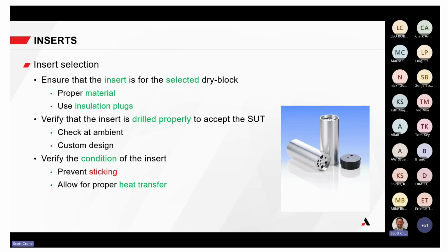Plus, you've got to make sure that the diameter matches. So typically, a high temperature and a low temperature won't match exactly. You want to verify that the insert is properly drilled to accept the sensor under test. Check it at ambient. Don't get it in there at temperature and hope that it works. Make sure it works before you do the test. You may need a custom design.